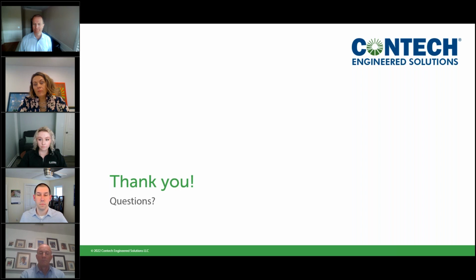Thank you, Dana. And our final question, with regards to maintenance of the system, what are your recommendations? I can take this. For maintaining detention systems, we usually put a minimum 24-inch riser, so you can get physical access to inspect as well as maintain it, not just a clean out port, but you can physically get inside. I would recommend pre-treatment, to be perfectly honest. Anything you can do to minimize trying to clean out a pipe system is going to make it easier to clean the pipe system. But obviously, if there is sediment going in there, even with a perforated system, it's still a solid bottom. So you can either jet and vac, or you can scoop and shovel. There are a few different ways to handle it. And we've got a whole maintenance manual that explains that, which you can dig into at a later date.